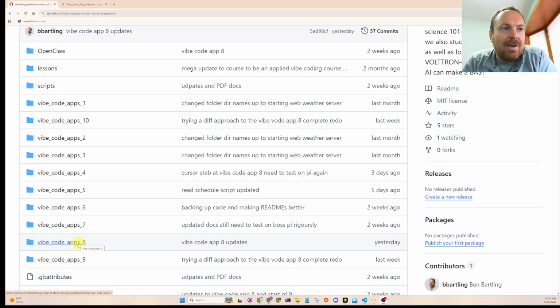Just a little recap: every building automation system these days is a web app. Usually they just run on-premise locally behind the firewall. They're not web apps exposed to the internet, like a banking website or something fancy like that. They're just a web app that you spin up that can read and write to BACnet devices in the building for HVAC control. We need to schedule the BACnet equipment, or the HVAC equipment, via BACnet requests.